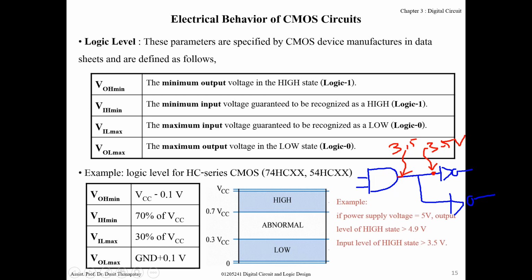If this signal is used through many logic gates, some voltage drop may occur. If it drops, it becomes lower than 3.5, for example 3.0 or 2.8. That means the signal level is now lower than logic high, so some operation may not be good.